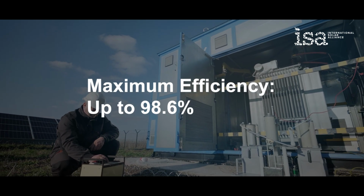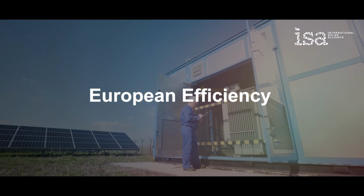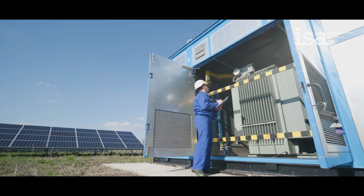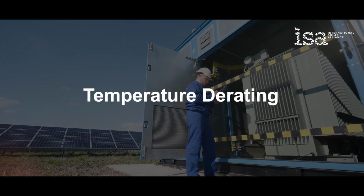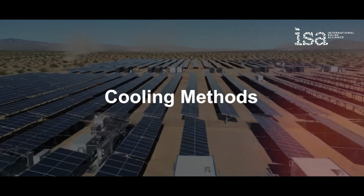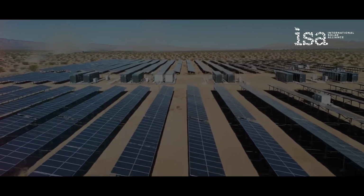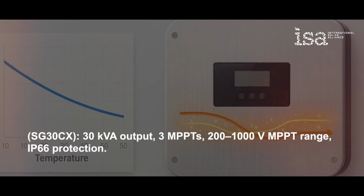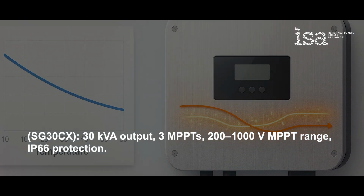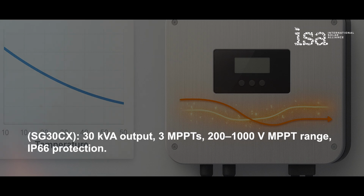Maximum efficiency is up to 98.6% for top-tier models. European efficiency reflects realistic operating conditions, approximately 98.3%. Temperature derating: output power reduces beyond 45 degrees Celsius. Cooling methods: forced air, natural convection, or liquid cooling. Example: SG30CX, 30 kVA output, 3 MPPTs, 200 to 1000 volts MPPT range, IP66 protection.